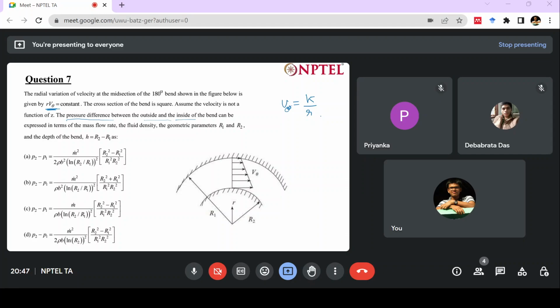Okay. So this actually does not correspond with the figure. The figure is kind of given as linear. Yes, sure, definitely a good catch. So since v theta is a free vortex flow, this is irrotational. Good. So you can actually use Bernoulli's theorem.